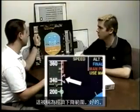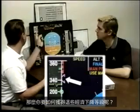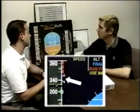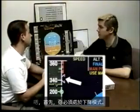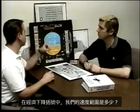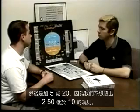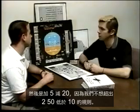We have these magenta brackets. What are those called? It's called econ descent range. Okay. And how do you get these econ descent brackets? Well, first of all, you have to be in descent mode. You also have to be in the descent phase of the MCDU. And then finally, you have to have managed speed. Okay. In the econ descent brackets, what's our range of speed? It's plus or minus 20 knots off of whatever we have programmed in the MCDU, unless we're below 10,000 feet. Then it's plus 5 minus 20 because we don't want to overspeed the 250 below 10 rule.